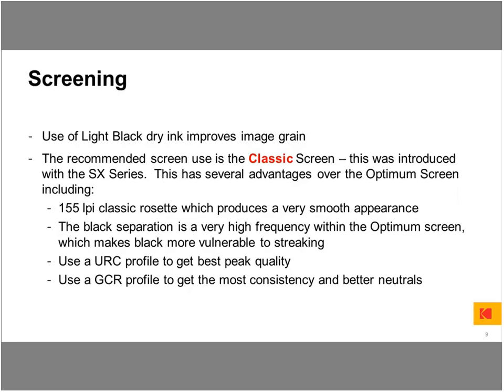The reason for the high frequency screen is that sometimes people do not want to see the halftone screen, because when they see that, they see it as lower quality. So by pushing the frequency up, it's more difficult for people to see. But at the same time, the higher frequency means that the halftone dot size is smaller. Numerically speaking, the noise is caused by the smaller dot. It's hard to control the individual dot uniformity across the page. Basically, that will result in a streaking problem.